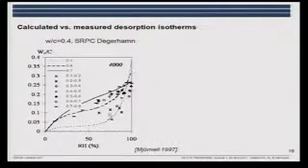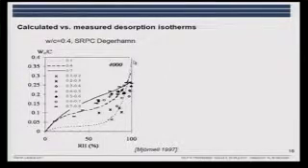Initially, we have a lot of free water, at low degree of hydration. And as the hydration takes place and we have more and more small pores, we will see that the sorption isotherm moves up, and we have many more smaller pores. And also what you see here is that we have a decrease in the total water content, because we don't have water from the exterior coming in and filling up the pores. We had this chemical shrinkage.